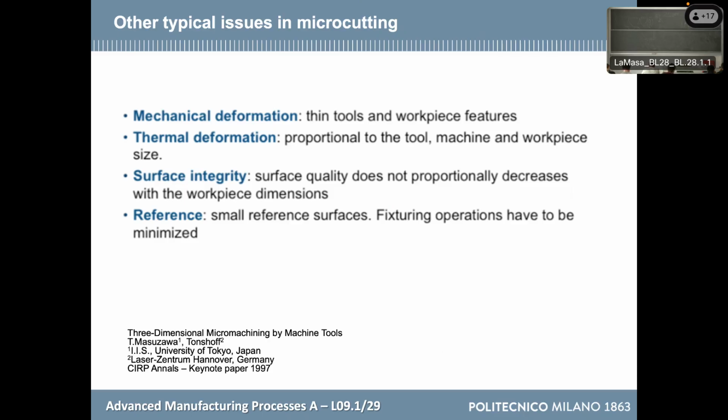I was talking before coming to the lecture this morning. I had a meeting with some colleagues of CNR, making filters for gigahertz transmission in space. A very fascinating application. At the end, what they want to have are small channels of, let's say, 80 microns, really sharp, because when the electromagnetic waves pass there, they are somehow filtered. I'm cutting the story really short. But with micromilling, but also micro-EDM, which is inside this course, you can make those fine geometries that act on the electromagnetic waves and are able to filter them.